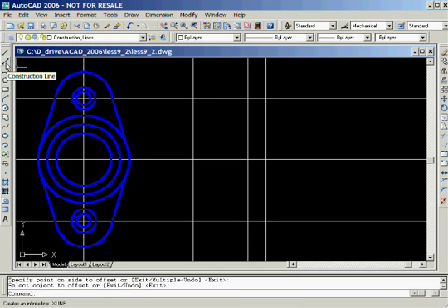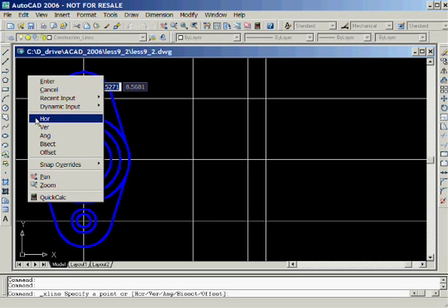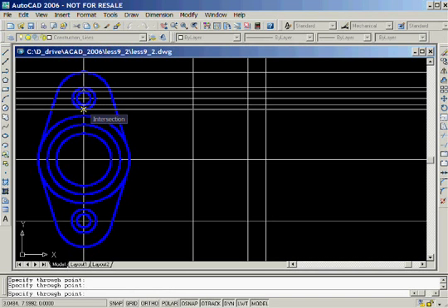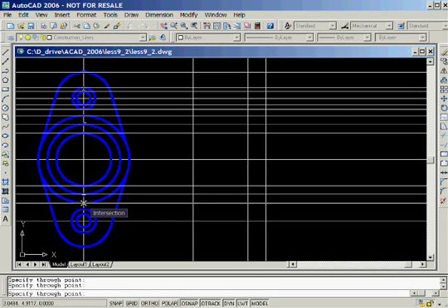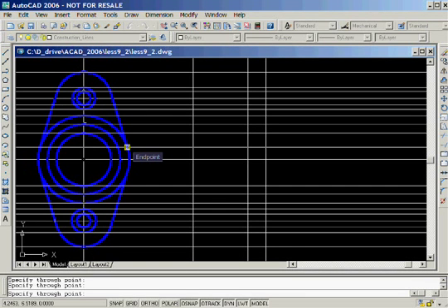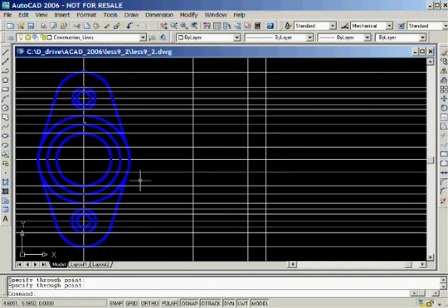We'll now jump to a point after we have used the Offset command two more times to create the additional two vertical construction lines shown here. The next step is to create projection lines between the top view and side view. We'll do this by first clicking on the construction line icon and then we'll right-click the mouse and select the horizontal option from the pop-up menu. We'll now click at each intersection location between a vertical construction line and the arcs and circles. We'll also click at the tangent locations.